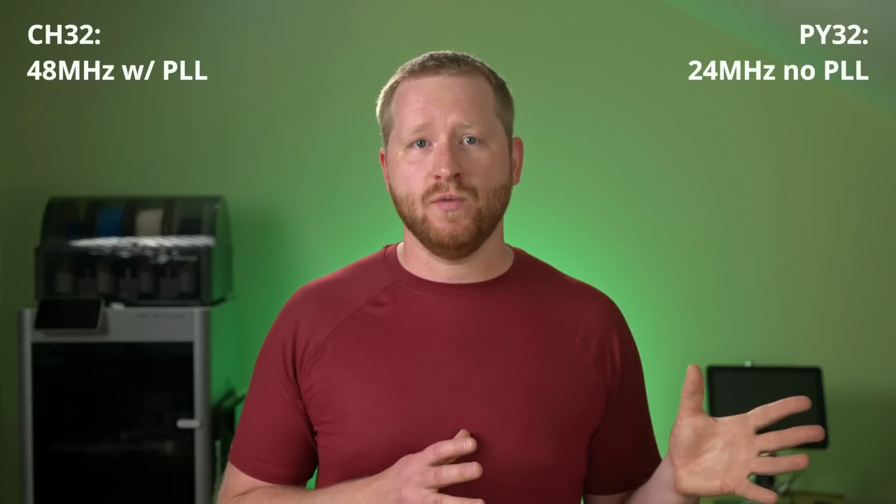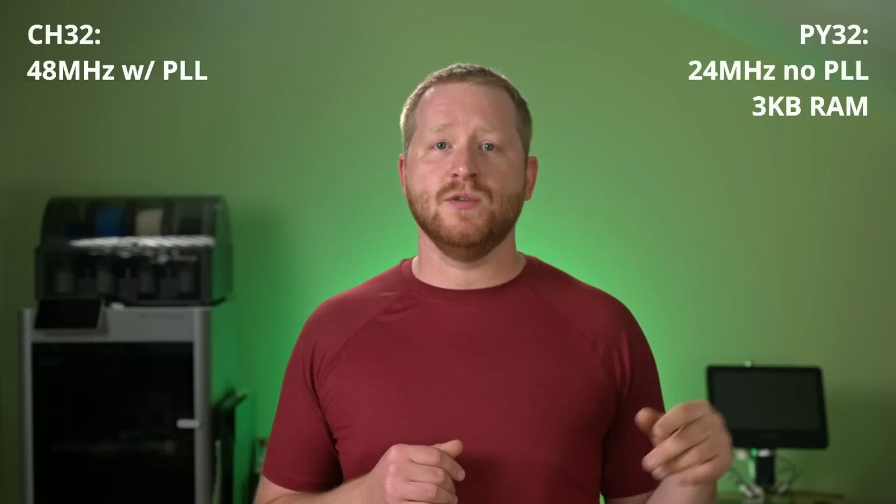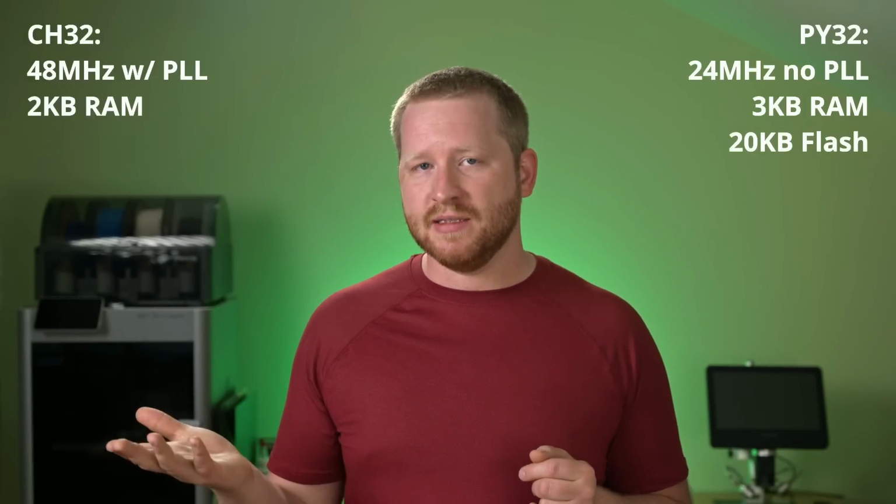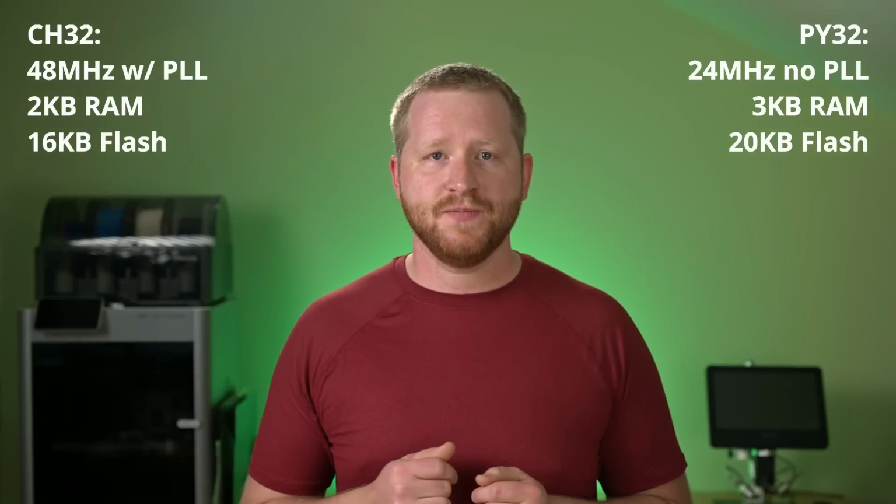To start, the CH32 can run up to 48 MHz, and it has a PLL that can make that frequency from the 24 MHz internal oscillator. The PY32, though, runs at half that, 24 MHz, it has no PLL. The PY32 does have the edge for RAM and flash, with 3 kilobytes of RAM and 20 kilobytes of flash, whereas the CH32 has 2 kilobytes of RAM and 16 kilobytes of flash.